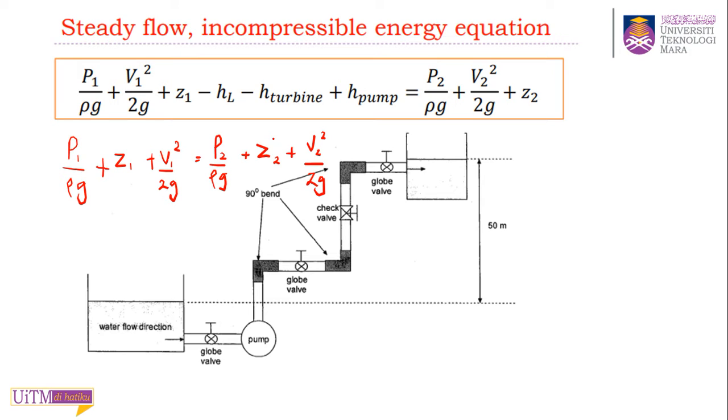There is no friction, that's why we don't add any mechanical device. It just flows by the pressure difference, and there's no heat in or out. Those are our assumptions, so that's why we can use this Bernoulli equation.